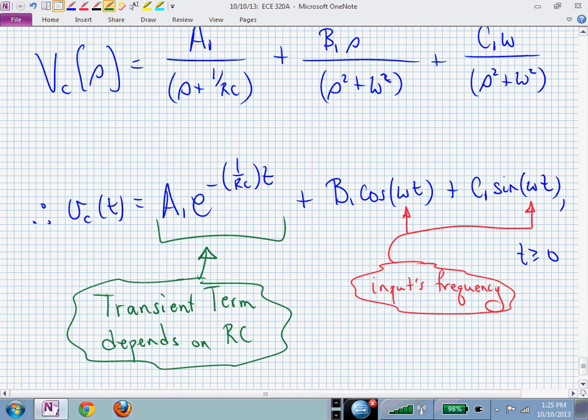All right, any questions on this? Is this helping with Laplace transforms? Do you now see what's going on? Now you can excite these circuits. Now your circuits can be much more involved. As long as you can derive the equation that describes the behavior of that circuit, now you just do what we've been doing. You multiply that transfer function by the input. It's Laplace transform, and you can find the output.